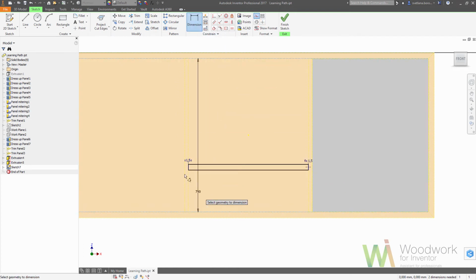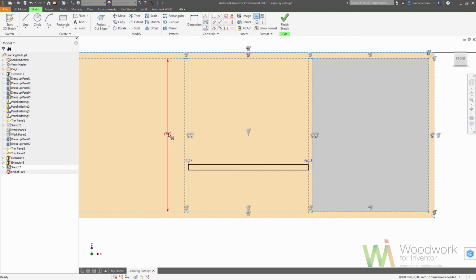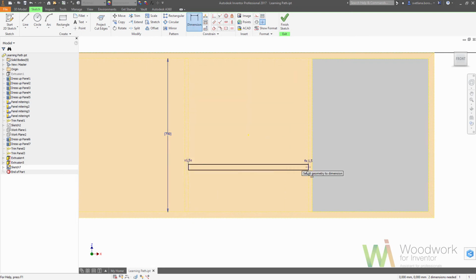So now we are making a reference parameter, which would be used to measure the height. So we can use the right click on it to change the name. So it would be called like niche height. Okay, now we can define the position like niche height divided by list parameters shelf quantity plus 1, because we are usually making a spacings, not the shelves.